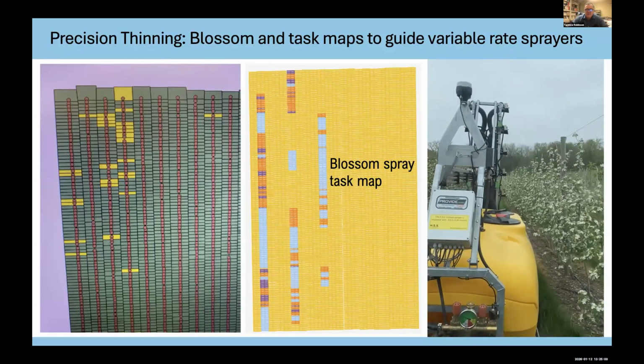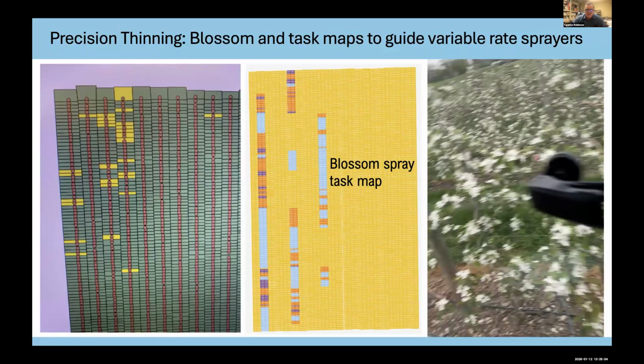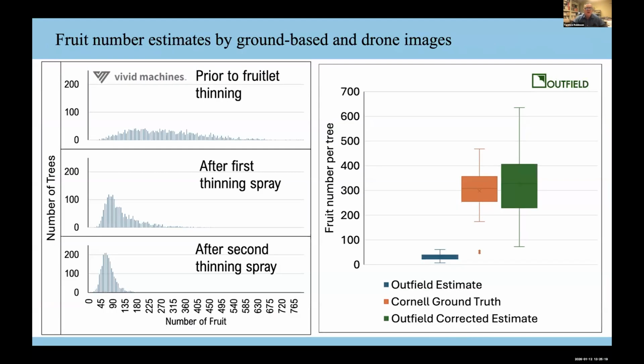There's a short video showing just on and off of the HSS system. Now, this particular sprayer uses variable nozzles, PWM nozzles, which would allow separately to spray the top of the tree to the bottom of the tree. Whereas most other sprayers, it's only an entire bank, either on the left side or the right side of the sprayer, gets turned on and off at any one time for any one tree.